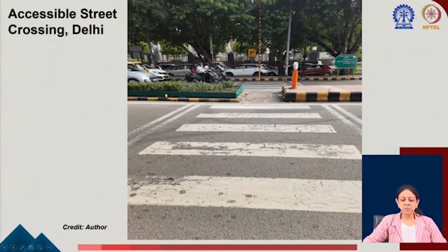A simple solution, what are called curb cuts. Like you have a median, but if someone is trying to cross the road, they are not stopped there. They can just wait here for the traffic to pass, and then cross the entire road. But generally what we see is that the medians are continuous. So a simple pedestrian cut-through in the median can be a lot of help.